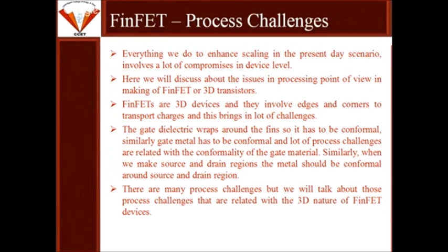The gate dielectric wraps around the fins, so it has to be conformal. Similarly, gate metal has to be conformal, and a lot of process challenges are related to the conformality of the gate material. Similarly, when we make the source and drain region, that metal also should be conformal around the source and drain region. There are many process challenges, but we'll talk about only a few that are related to the 3D nature of the FinFET device.